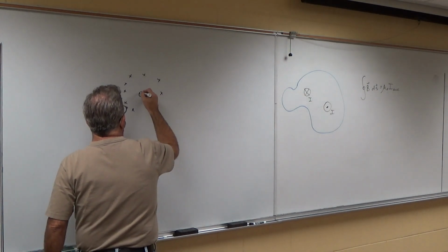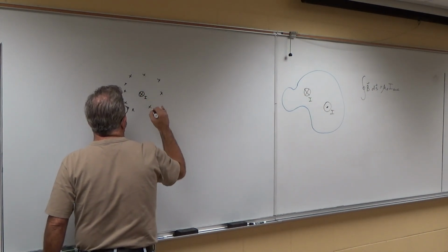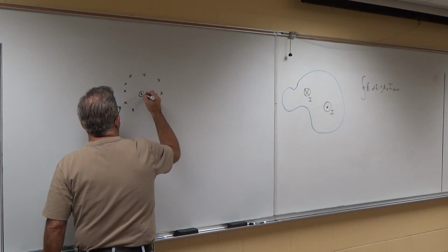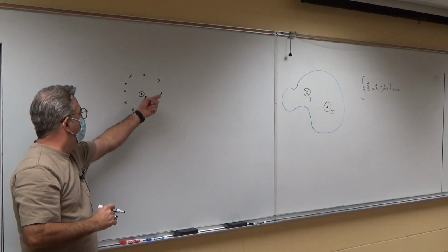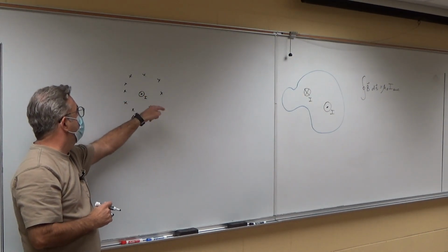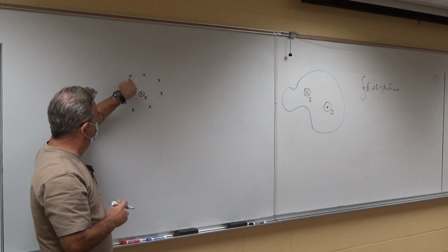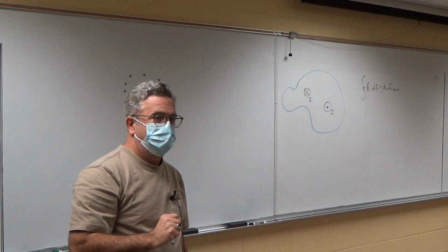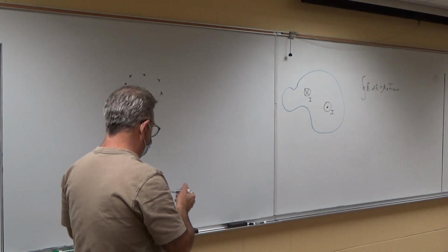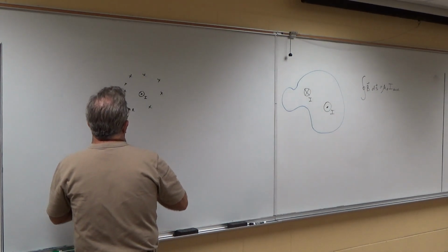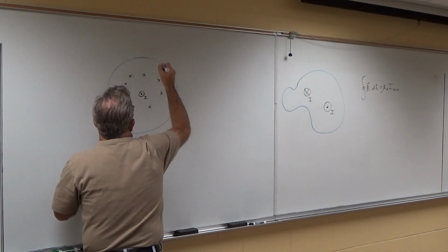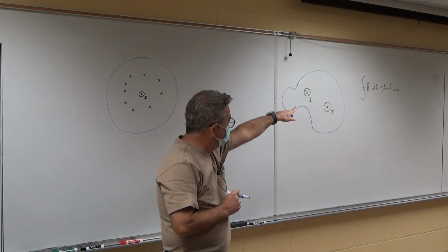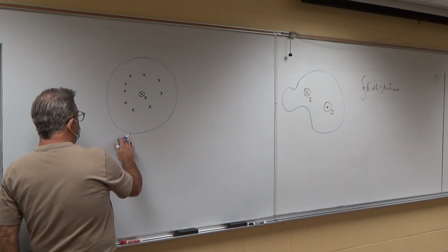Coaxial cable is nice because if you have, let me change that around since I made these X's. If you have current flowing out of the board in this direction or current in this direction, that shield or that outer conductor, the current's all flowing in that direction. And Ampere's law says if you enclose it in a loop, okay, like this, and you calculate the B dot ds, you're going to get 0.